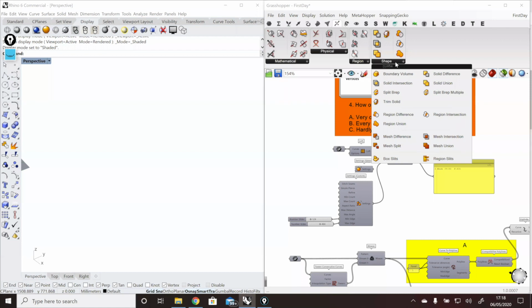In general, converting a mesh to a brep is very difficult, and there are some plugins to do this, Pufferfish, for example, has that. Yes, but they are not the most stable. No, exactly. It's not something that I would recommend doing. So then you do have mesh Boolean operations, but same thing, they're going to be really computationally expensive.